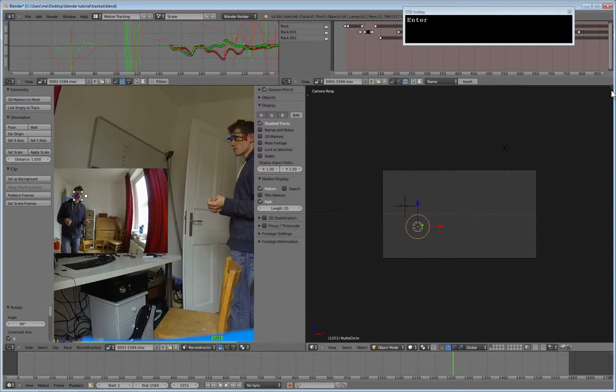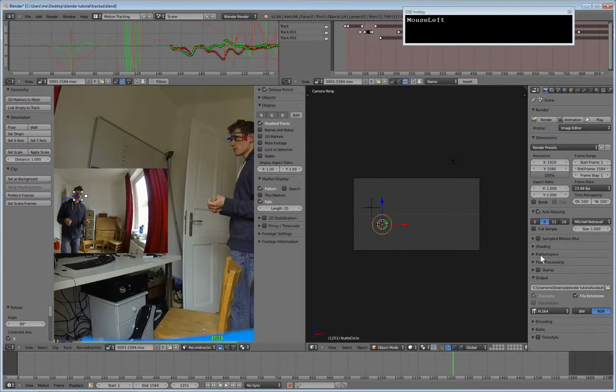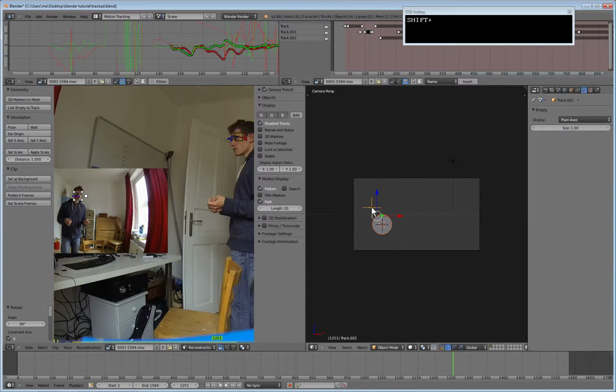So once again we split our working place, select this to reflect properties, and in the properties pane we go onto the paths tab and select the shape for the wireframe to be 2D and create a surface. And then we take the surface and shift select the empty object, and with Ctrl P we parent the disk to the object.